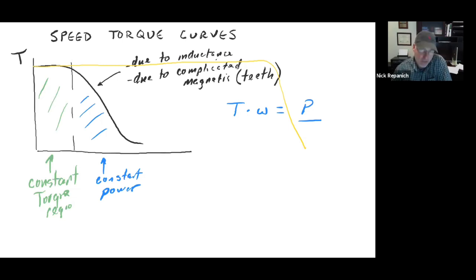So we're limited to high torque and low speed with these steppers, which is perfect for this application. You're after high torque and fairly low speed. So this point right here, I'm going to actually put a number on it. This is speed. Oops, wrong color. You've got to get more practice at speed. I'm going to put a number on this. This is probably 10 revs per second. I'm going to say 2 to 10, something in there.